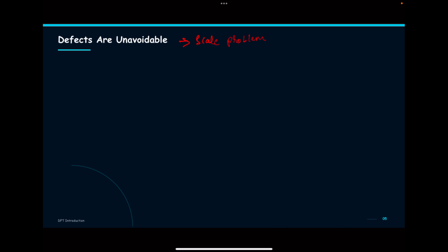Why can defects not be completely eliminated? Even though semiconductor manufacturing happens in highly controlled clean rooms, it is still impossible to make the process 100% perfect. For example, a tiny dust particle can land on the wafer and accidentally short two metal wires. During photolithography, the light exposure may not be perfectly uniform across the entire wafer.